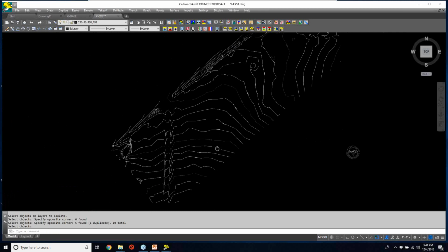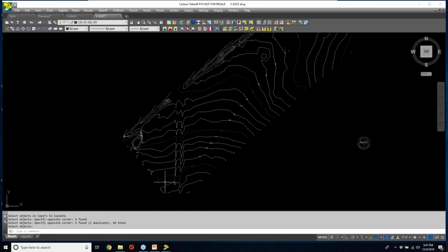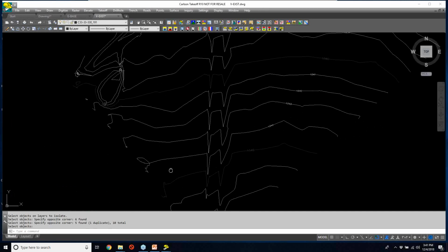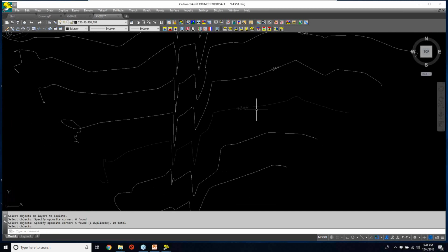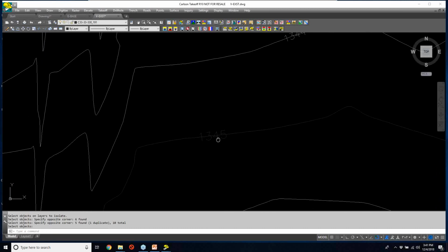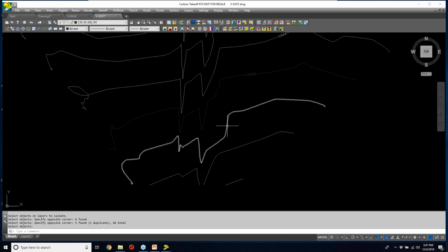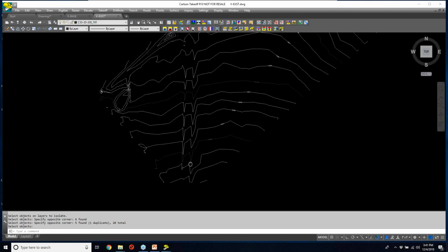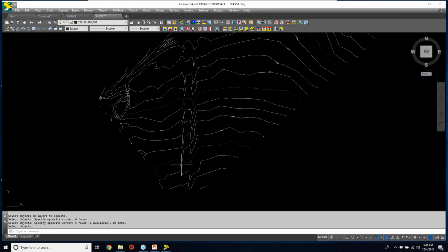So what I want to do now then is get these contours elevated. And for the sake of starting this off, the last piece of annotation in here I was at, it was 1345, there was 1344. This must be a 1346. There's a 1347, and it's disjointed right here. So I'm going to say, well, let's say that this first one is a 1347. I'm going to go right to this little, probably a little depression right down in here. So I'm going to elevate all these contours in one shot, going right down to the bottom of that one, slope direction.